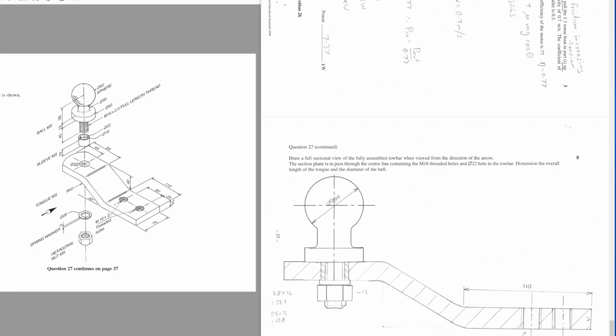And so I put my center lines in. And once I did my center lines, it says here that this is an M16 threaded hole. Now, with threaded holes, the major diameter is the outside diameter, and the minor diameter is the inside diameter. So it's worth noting that the dark line is the inside line and the light line is the outside line, and that when we hatch into that, because it's empty, there's nothing there, we have to hatch into there.